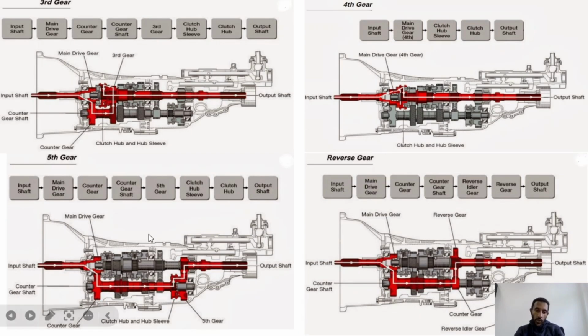And if you observe the fifth gear, it's out of the intermediate shaft, in the intermediate plate, and if you see the size, it is very big, and this one, the output side, is small. We call this one OD, overdrive. So 1 to 3 are underdrive gears. This one is direct drive. This one is overdrive, which means the engine torque will be multiplied and go out, but the speed will be reduced because torque and speed are inverse.